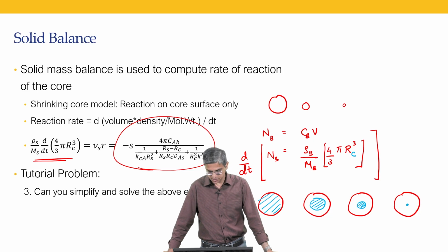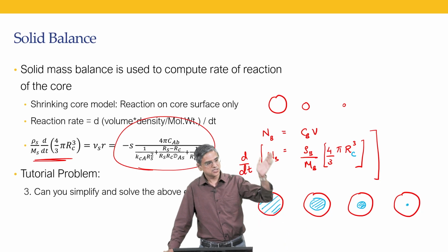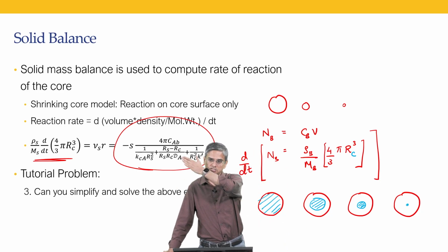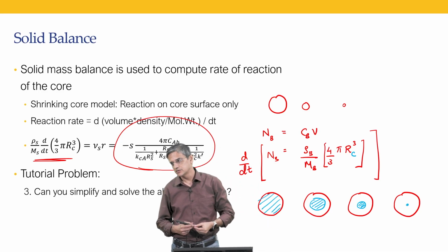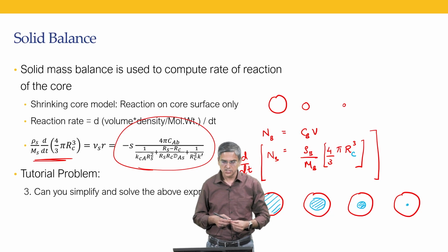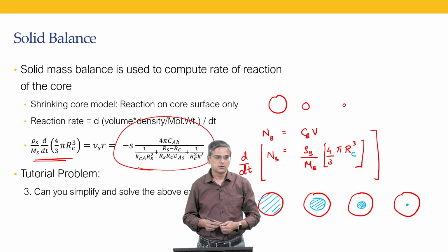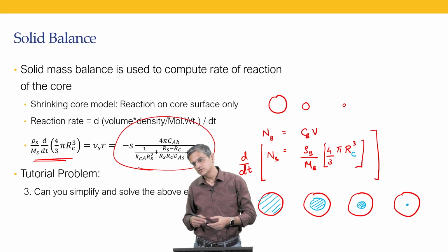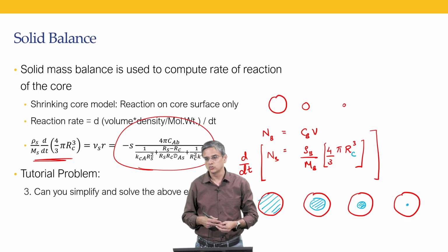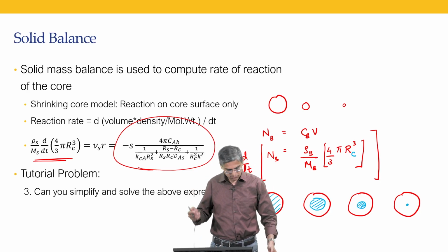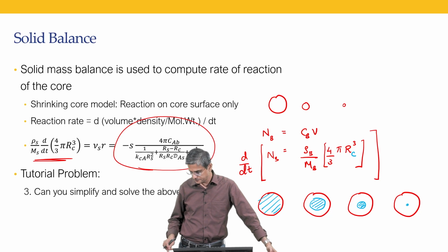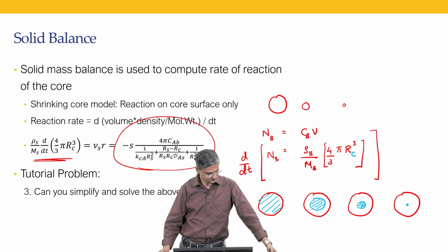Okay. So, in that case you have a reversible reaction, A plus B giving P plus Q. So, in oxidation it is A plus B giving P plus Q, in reduction it is P plus Q giving A plus B, and you keep doing this in a cyclic manner. Okay. So, chemical looping reactions are one of the things that people are beginning to use in order to address the issue of over oxidation and improve the efficiency in catalysts, and thereby address the problem of CO2 emissions.